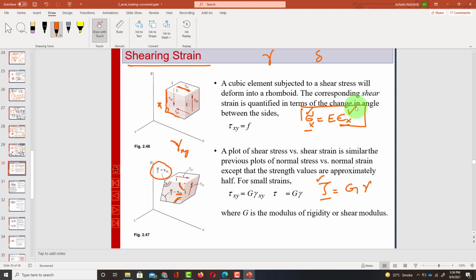This is strain, that is linear strain, and this is strain but shear strain. This is E, which is modulus of elasticity, but here this G is known as modulus of rigidity. So this is for linear system and this is for rotational system or tend to rotate. ठीक है ना? So it is analogous of force analogous of rotational system. So हमारे पास जो है वो shear stress बराबर है G into gamma simply. ठीक है ना? Clear?